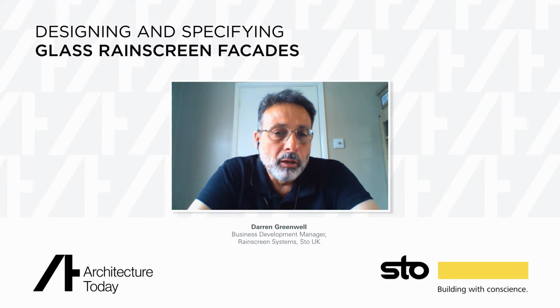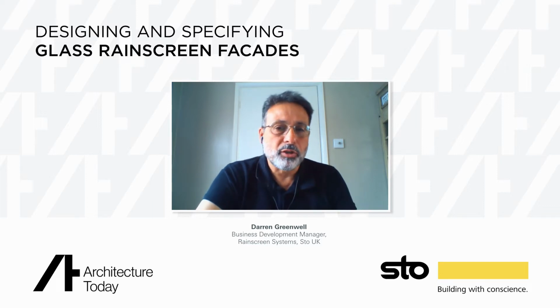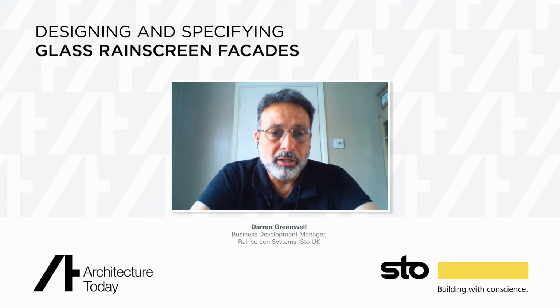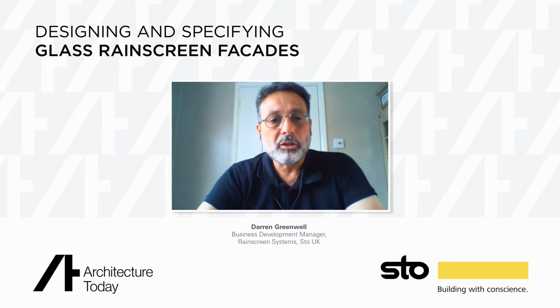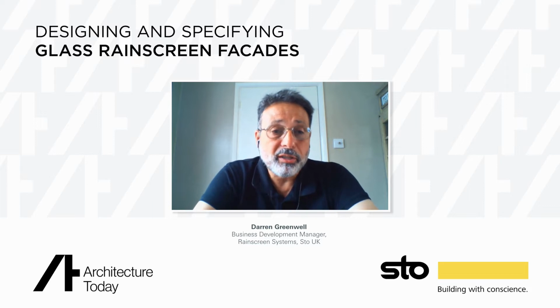In one instance, we had an architect who wanted lots and lots of triangles, which in practical terms, when you're using an open joint system, makes it difficult. So what we did instead was we printed the pattern on rectangular glass to achieve the same aesthetic. So the cost saving was significant. So again, it's always good to talk to us about options on sizes, patterns, colours, that sort of thing.